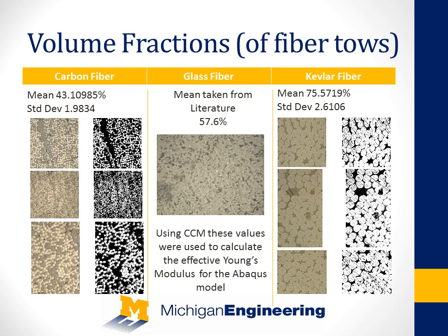Now, I use these volume fraction percentages in a CCM model, which is the concentric cylindrical model, which gives me an effective Young's modulus taking into account the fiber modulus as well as the epoxy modulus, so that I can upload isotropic material properties or transversely isotropic material properties into my Abaqus model.